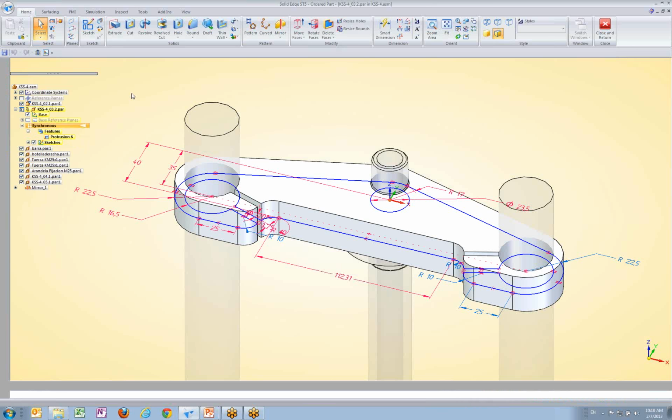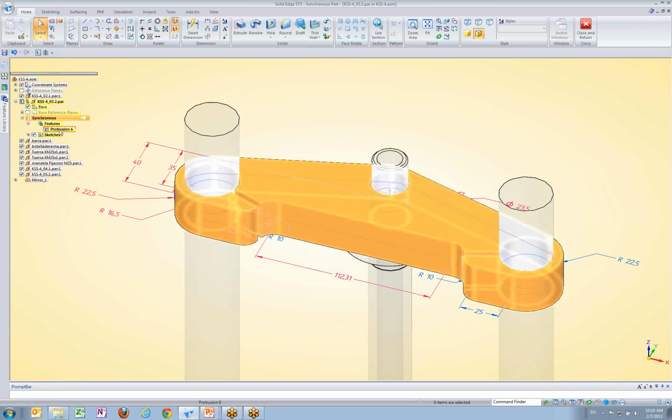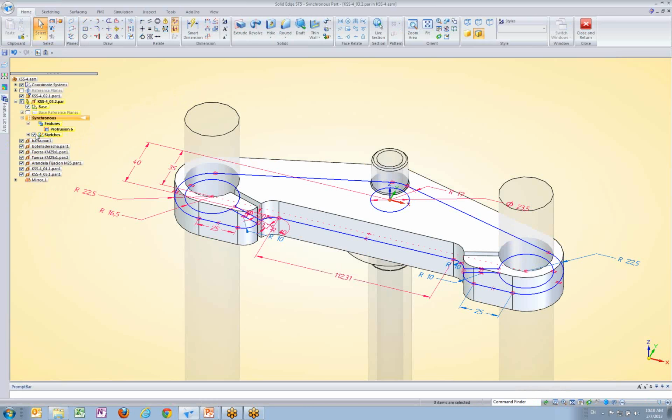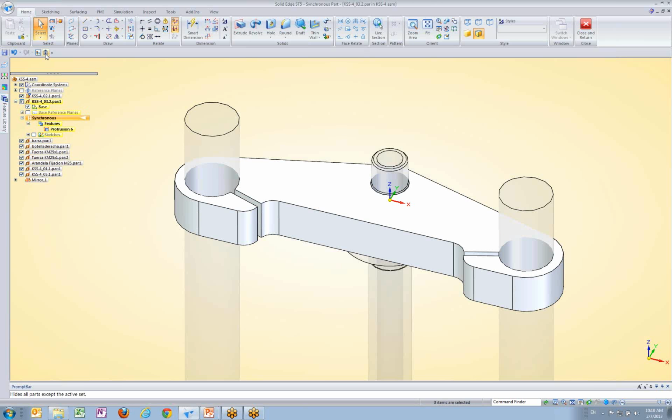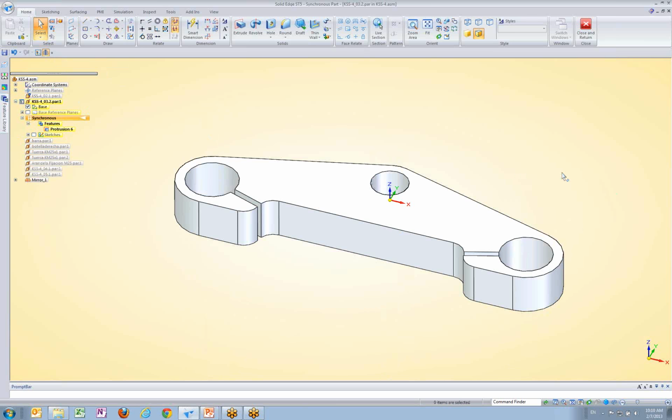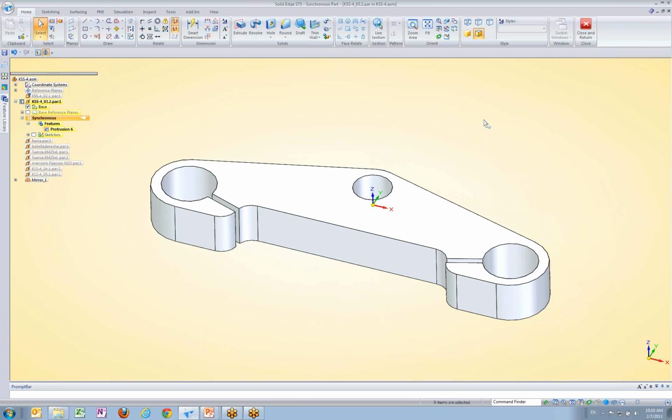And if I click on that synchronous just to bring me into that environment, you see there's the feature. It also brought the sketch because, of course, the feature was dependent on the sketch, but that's no longer the case. I'm going to uncheck this sketch and, again, hide my previous level. And now we've got the exact same features we did before, but we can interact with it synchronously.